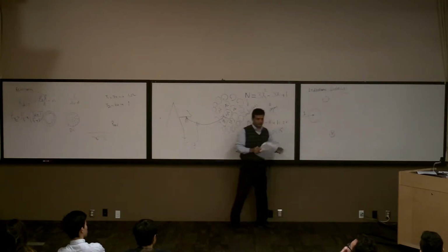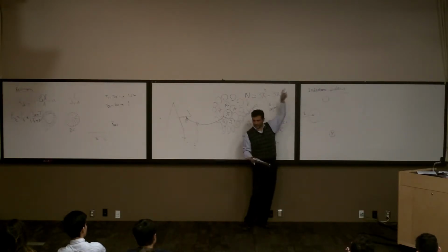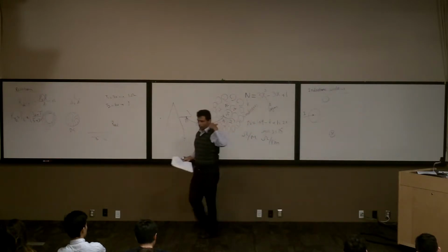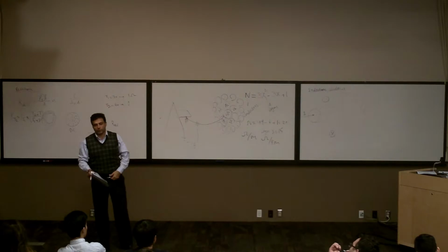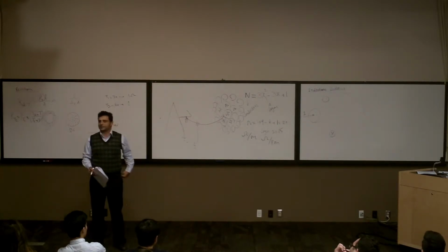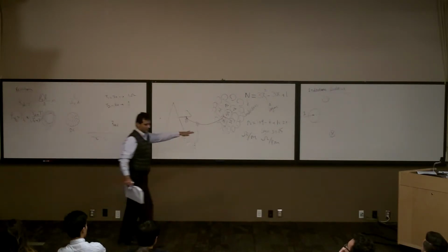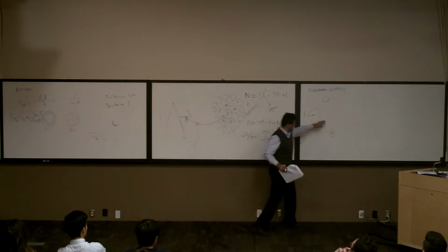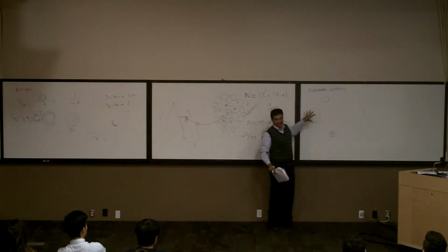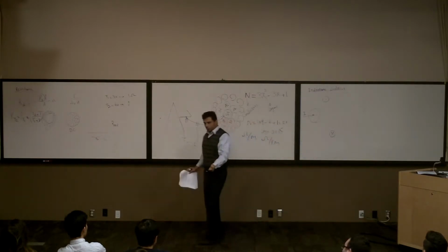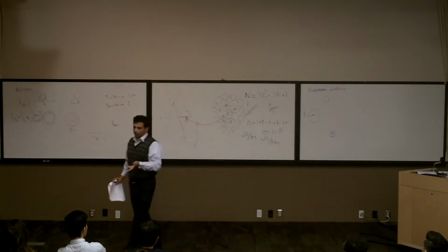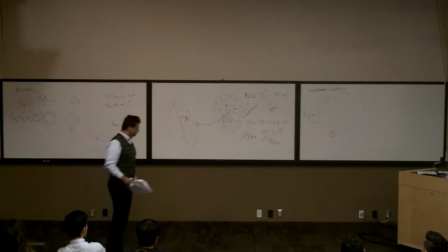This is the flux, right? It's going like this, right? But inside the conductor also there is some flux. We are going to calculate those things. We call it internal flux and external flux. External means this is outside, the flux going here, and internal is what we have inside this one. So the total inductance is going to be L internal plus L external. We calculate each one separately.